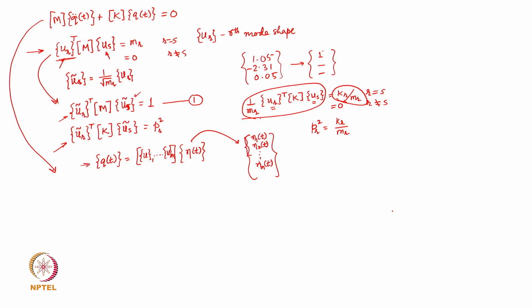We have already discussed this equation and shown how it works. Now, because these modal vectors are, I mean, if u1 is a modal vector, a constant times u1 is also a modal vector, right. So, I can use this matrix represented by U, and all of the elements of this matrix U are mass normalized modal vectors.